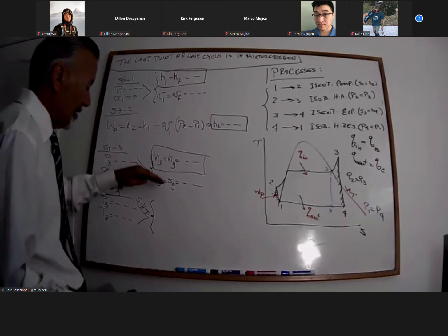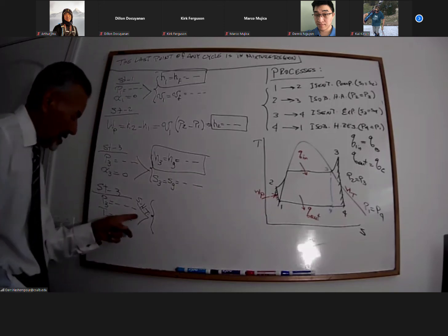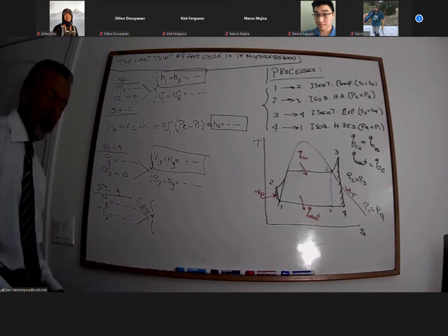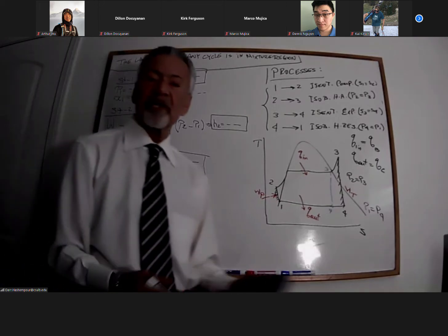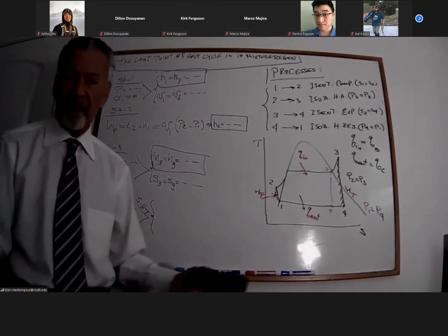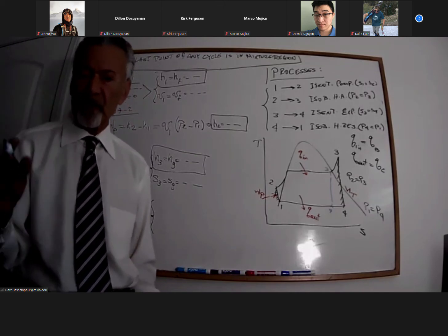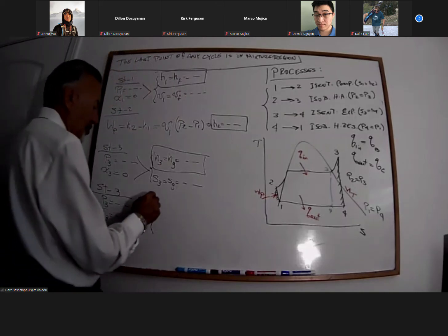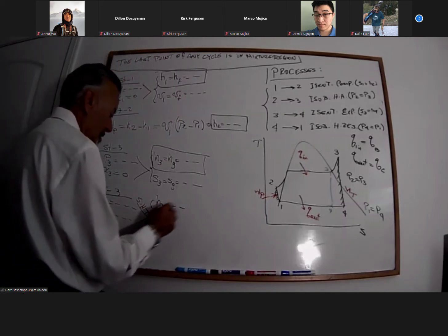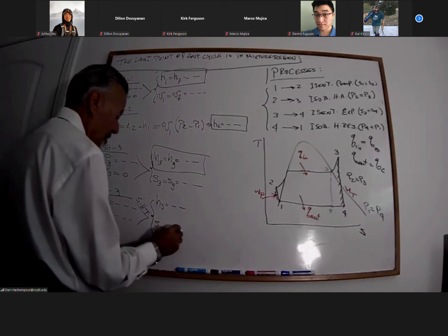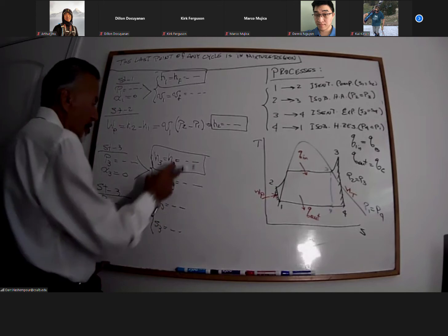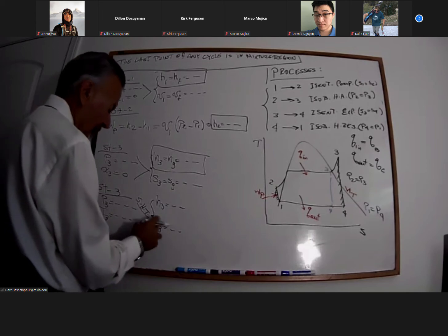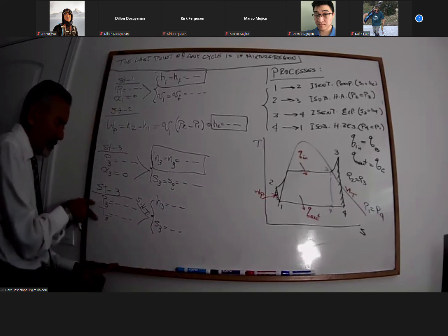So far, we were looking at just the saturated liquid table. Here, we go to the superheated table. When you go to the superheated table, you don't find H of F, H of G, or V of F, none of those. You just find S value, H value, that's it. So it's pretty easy. So you find H3 and S3. You no longer have H of G or S of G or any of those. Just H3, the value of H and value of S based on these 2 points of reference.